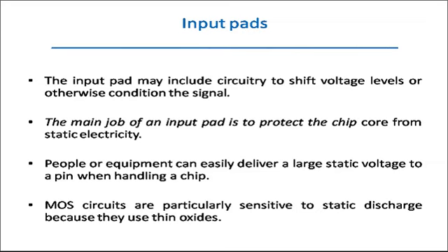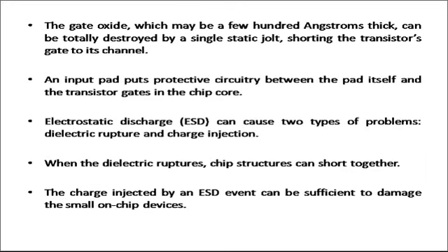Why? Because your body may have a certain static charge, and that static charge may damage the MOS circuitry, because most of the ICs are made up of MOS, and MOS is very sensitive to static discharge, and because of this static discharge the thin oxide may get damaged. That's why, whenever you are designing an input pad, it has to do the work of protecting the core logic.